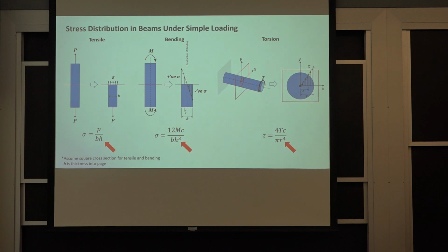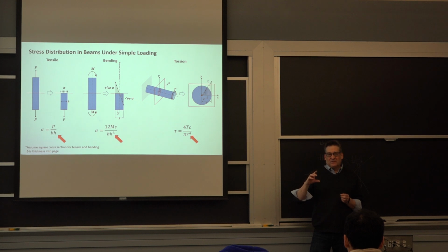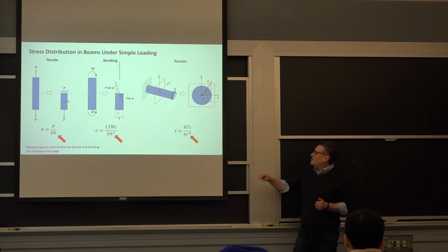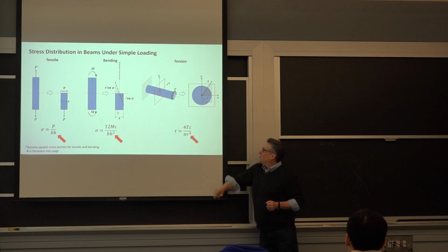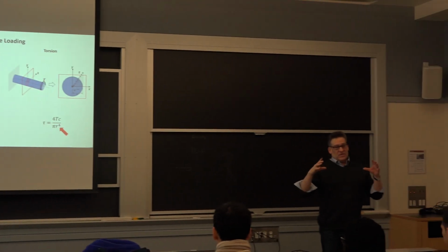Torsion is similar to bending in that you can think of a neutral axis of torsion where the shear load is 0. And then as you go away from that center axis, the shear load increases, so you hit a maximum at the outside of that tube or rod that's in torsion. Okay, and then there's a similar law here where the shear stress goes down as you increase the cross section of this rod. As you increase that, the stress goes down very quickly.